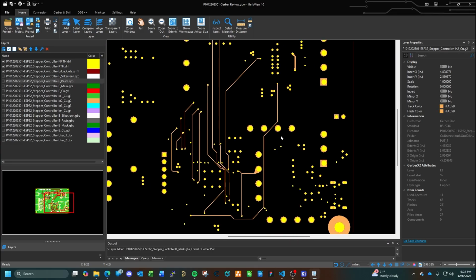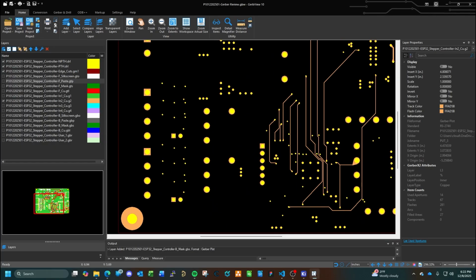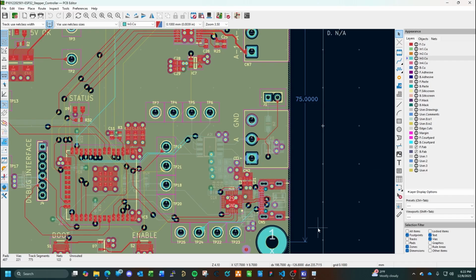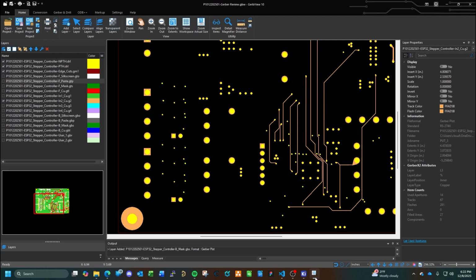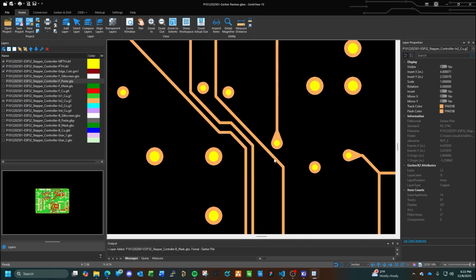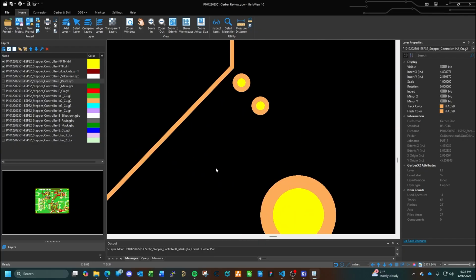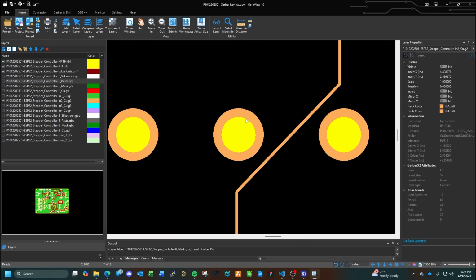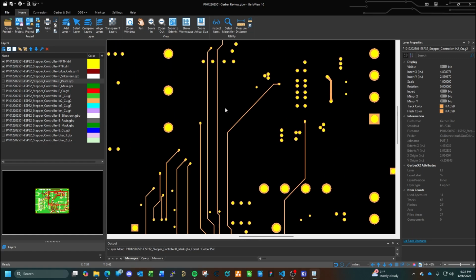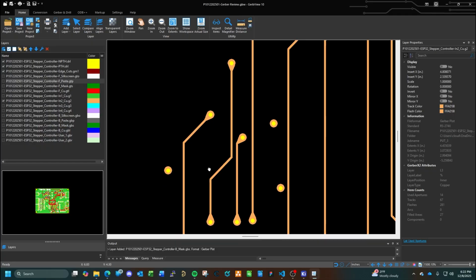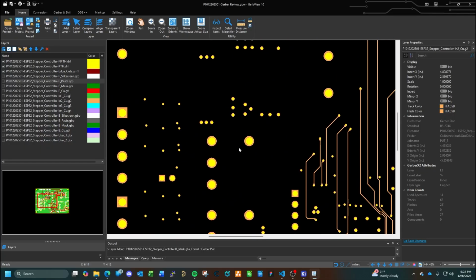This is an inner copper layer, the first signal layer. So in KiCad, this will be this layer right here. Again, you want to make sure that any signal lines aren't touching. You don't have extra copper. You don't have anything encroaching, especially your signals. That you're not accidentally touching a via. You're not shorting anything out. All your teardrops, everything's formed properly. That's all we're looking for.